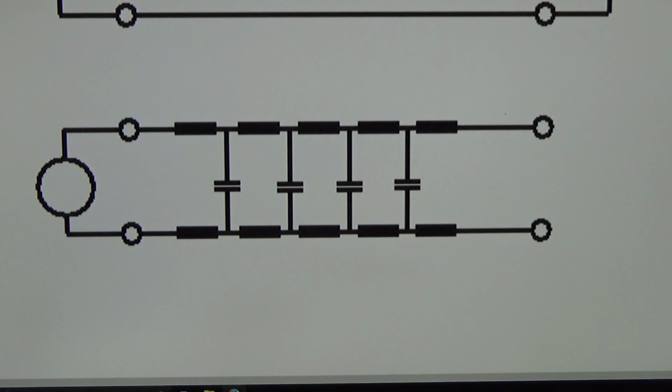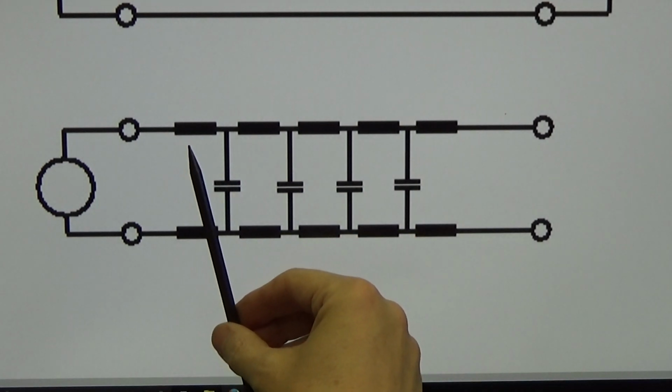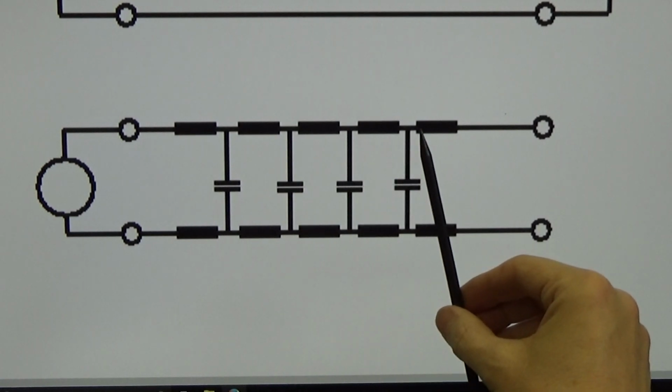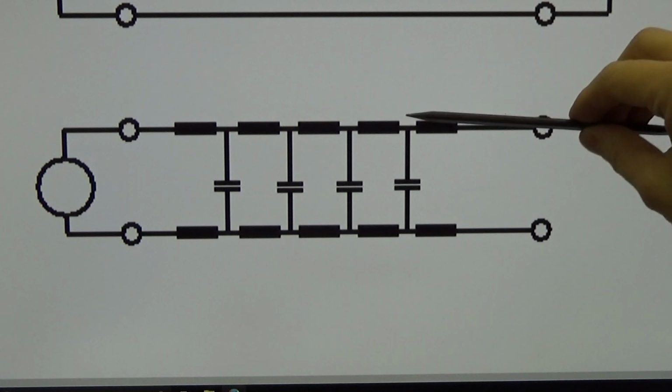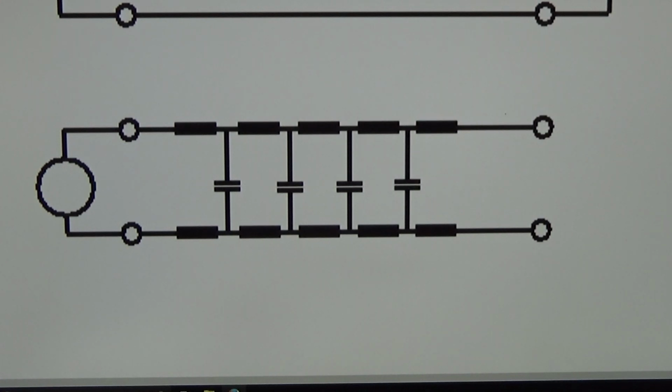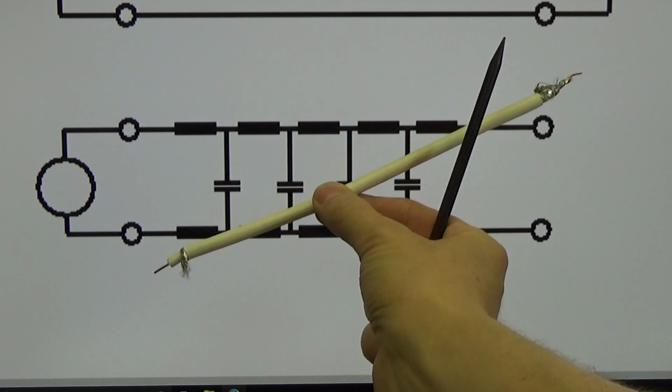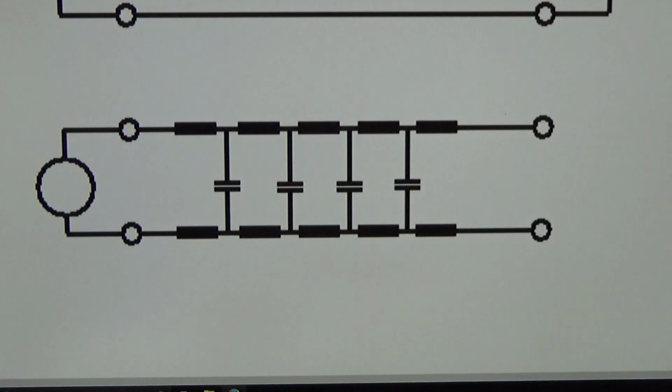So what we are looking at in our formula is really the ratio, and as the equivalent circuit diagram is like this, even if it is longer, the ratio of L and C is always the same, no matter how long your test piece is. So that is what you need to know.